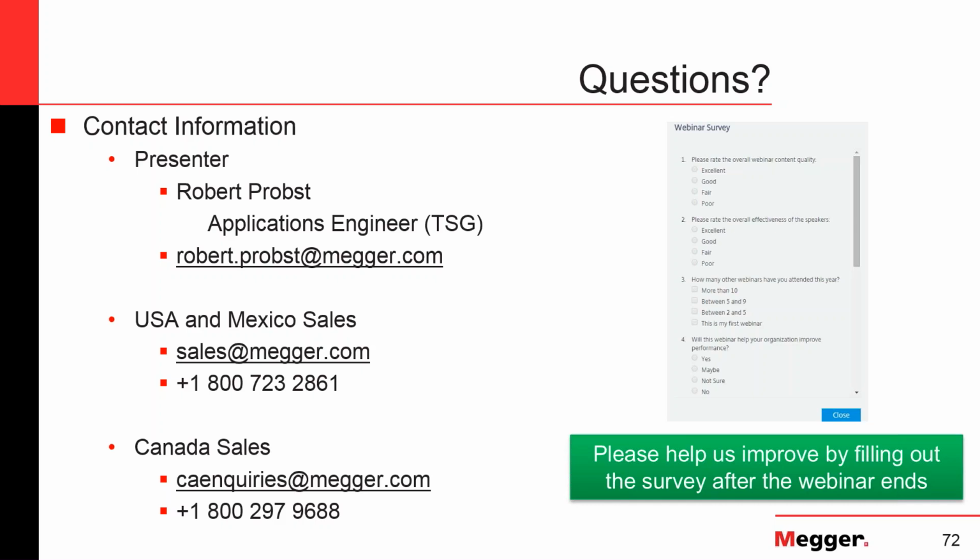If you have a source of limited power, you can either generate very high voltage and very low current, because your power is restricted. Then we're talking about insulation testing, a high voltage test at very low current. And the opposite is primary injection. There, you transform the voltage down and transform the current up to very high currents. And as John said, less than 30 volts.